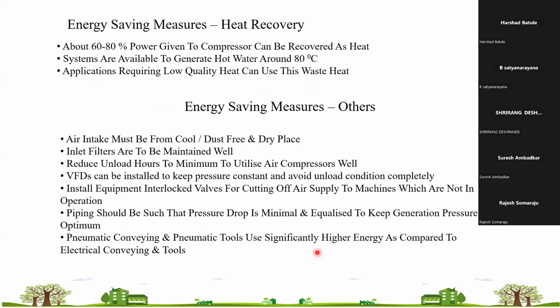Then another energy saving methodology is the usage of a variable speed drive. What does a variable speed drive do? You have an induction motor, you are generating rpm, and you are rotating that particular screw element. So you are generating more air delivery. Let's say you are generating 200 CFM, but your plant requires only 100 CFM.